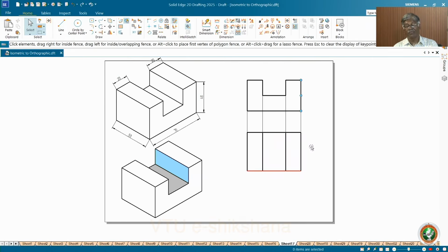Yes, see. So this should be 0.5 in your case. Okay. Let me take the next object. Let me block this. Say for example, here for a width of length of 50, I have a through channel, square type. Now let me block this at a distance of 25 mm and close at 25 mm before.